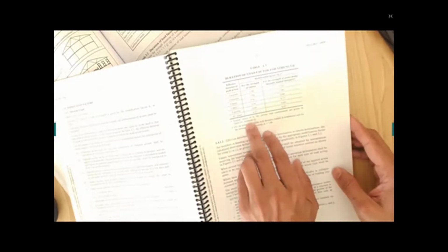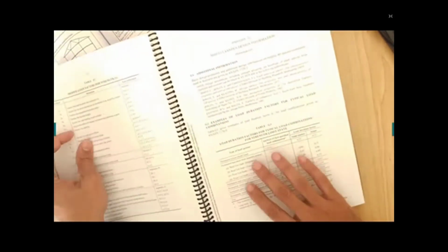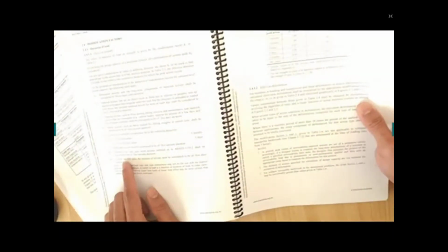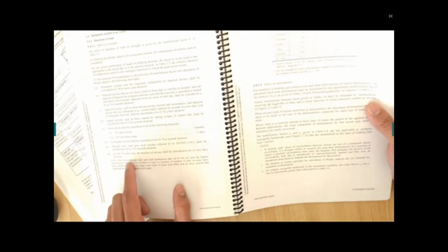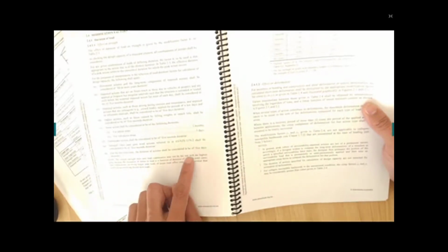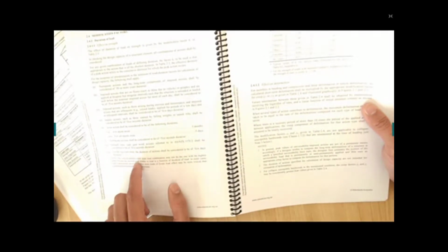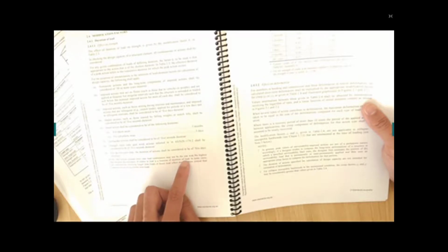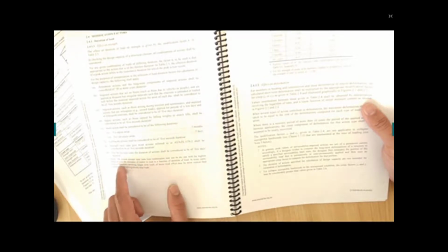So in that case, you need to go to Appendix G. Now in Appendix G, you have various load cases, like they have mentioned here. For strength limit, the critical strength limit load combination may not be the one that is the highest value, because of the resistance of timber to the load function, the duration of the load. In some cases, you have questions there?